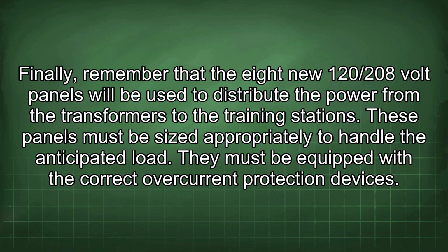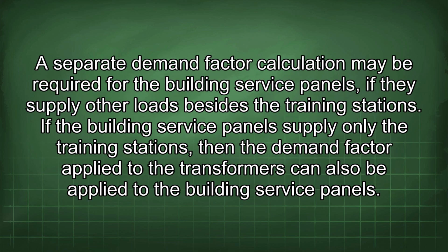Finally, remember that the 8 new 120/208 volt panels will be used to distribute the power from the transformers to the training stations. These panels must be sized appropriately to handle the anticipated load. They must be equipped with the correct overcurrent protection devices. A separate demand factor calculation may be required for the building service panels if they supply other loads besides the training stations. If the building service panels supply only the training stations, then the demand factor applied to the transformers can also be applied to the building service panels.